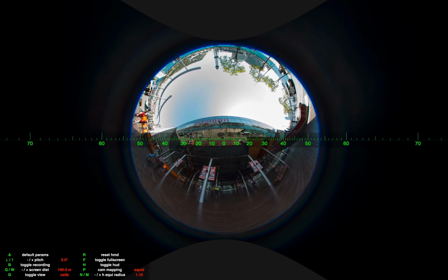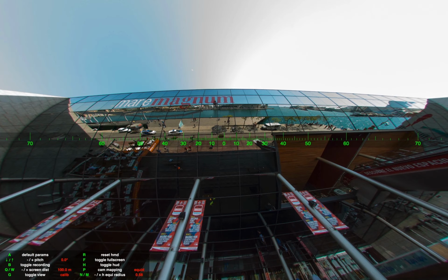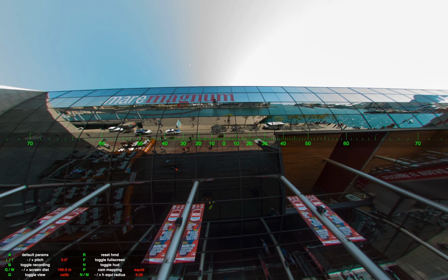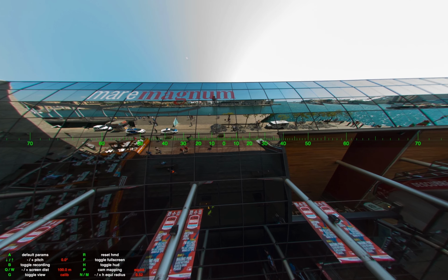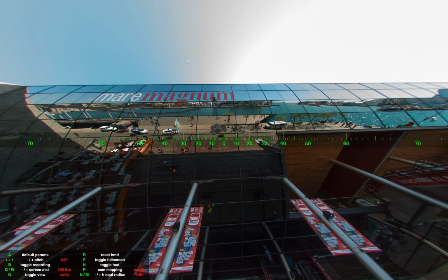Radius of 1 means that the circle goes exactly from the center of the image to the right, respectively left border. As you can see, this radius must be chosen too large because the distortion is still very visible. So I have to decrease it. I hold the N button until I get the correct value for this radius, and it's very simple to set it up because you have just to find the value where straight lines become straight again. So I think this could be a good